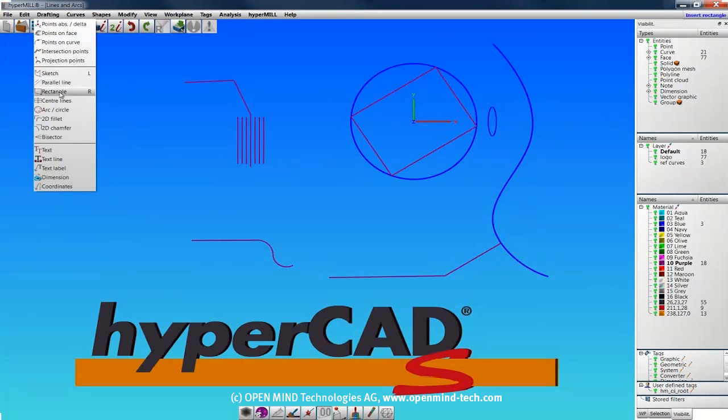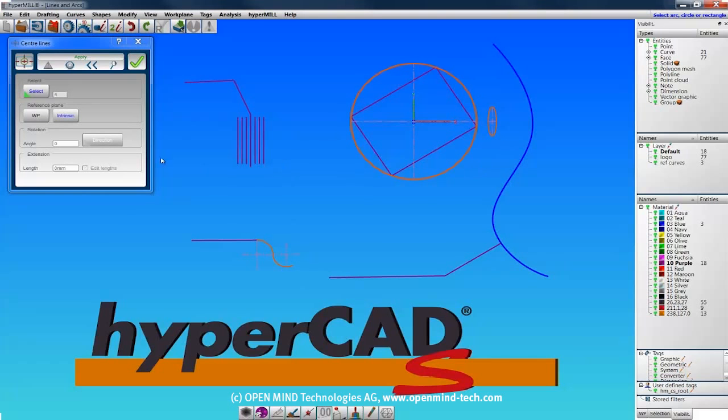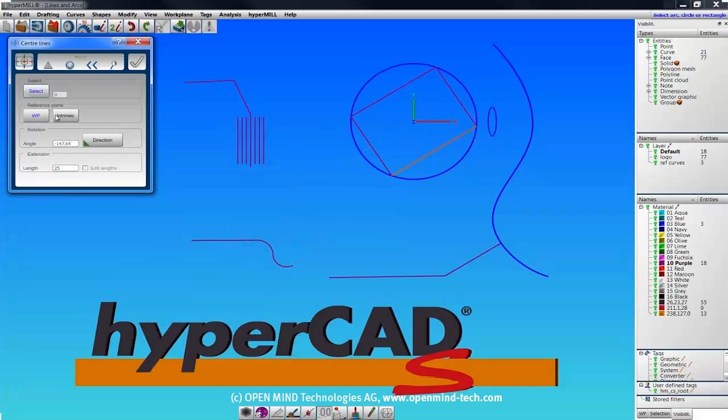The center lines command creates center lines on arcs or circles. The reference plane can be the work plane or intrinsic, meaning the plane of the arc. The rotation angle is measured from the x-axis or can be specified using the direction of an existing entity. The extension length can be globally edited or individually edited when working with a single arc.